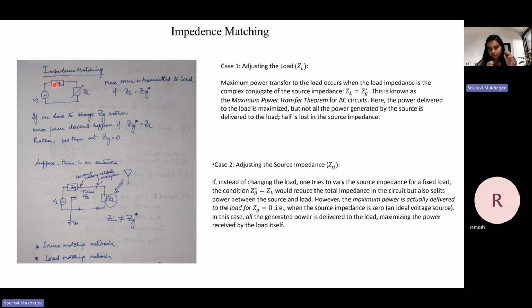It's important to note that this was one of the questions last time, where there are two situations. One is the case of no reflection, or when the VSWR is 1. That's the case where the characteristic impedance of the line should be equal to your load impedance.